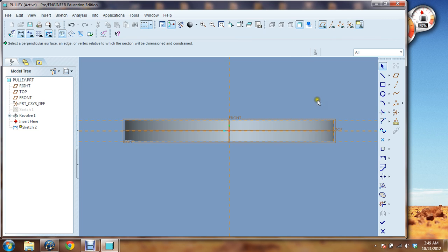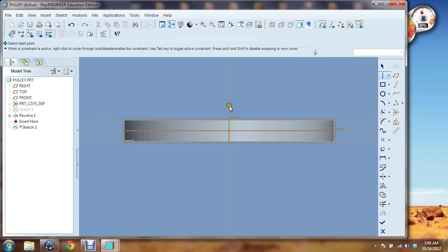And now we're going to revolve this sketch again. So I'm going to go ahead and make my center line now. It's good practice as soon as you start your sketch to make your center line, that way you don't forget. Because I don't know how many times I've made a sketch and wondered why it's not revolving, and the whole time I never had a center line. So I'm going to come up here to our rectangle and lock it to the top center of our plate.